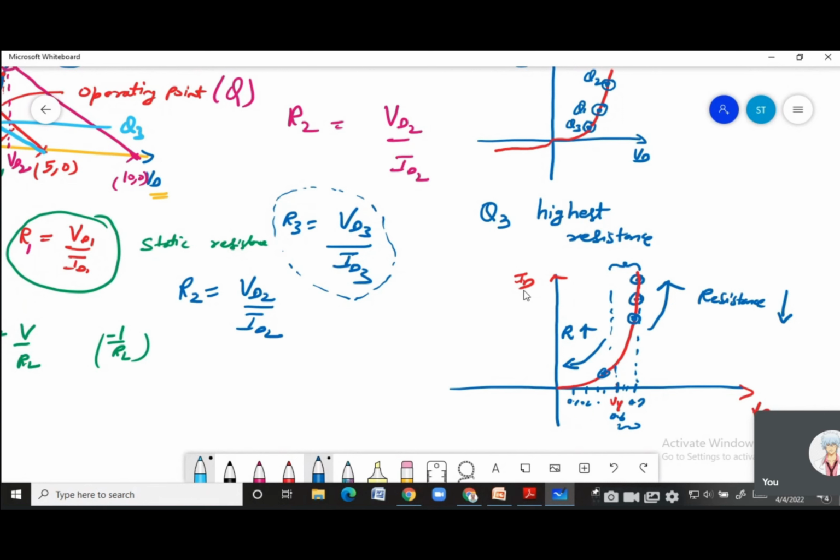Because the answer is that for a given variation in voltage, you don't get much current increase when you are below the cut-in voltage. And that's why, if you look at this characteristic, it's an exponentially increasing characteristic. So if you are somewhere here, on top of this characteristic, then you have the lowest resistance of the diode. So the resistance of the diode is varying with the external voltage applied.